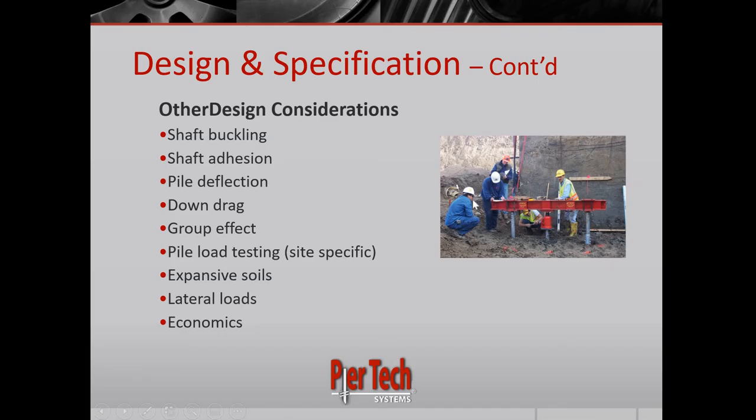Here's an example of a very light loaded pile test, just two reaction anchors and a cylinder being loaded up. This is a verification method for verifying that you've reached the capacity you're looking for.